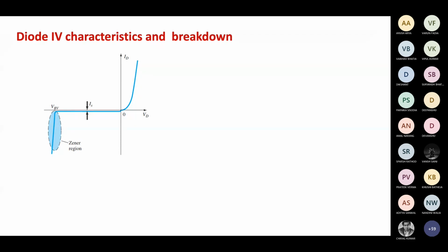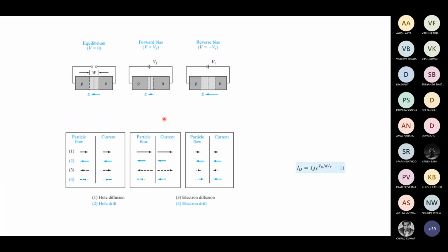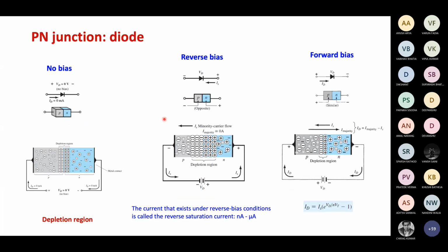You might have seen this graph at many places, I guess. This is the IV characteristics of the diode. So that is essentially the relationship between ID and VD. And so what I was trying to point out is that although this equation might look very simple, like an exponential equation, it contains many different physical processes going on. It contains the drift, it contains diffusion, it is dependent on temperature, it depends on device geometry, construction, external parameter VD. So it contains a lot of physics actually.